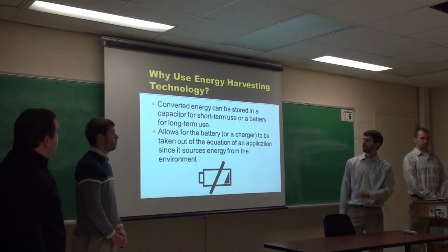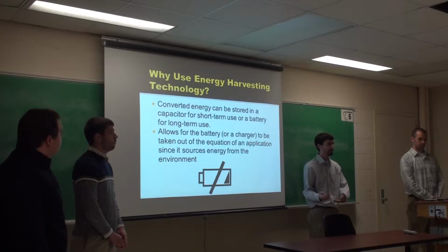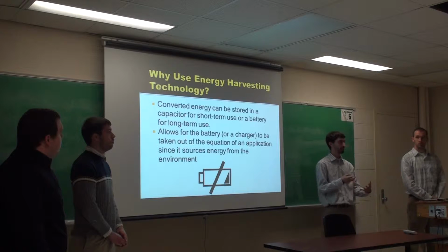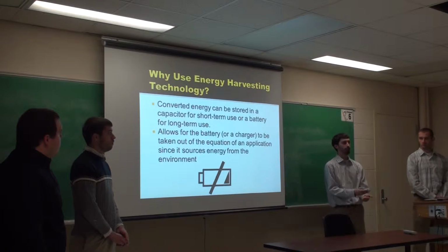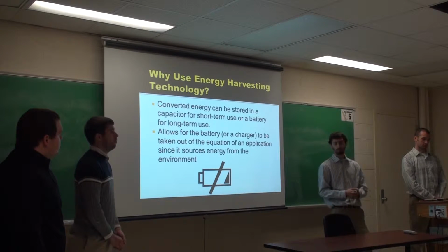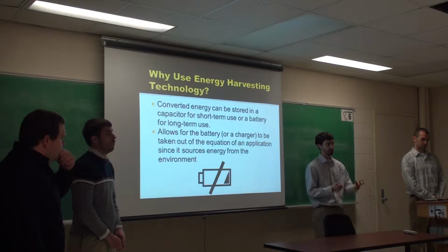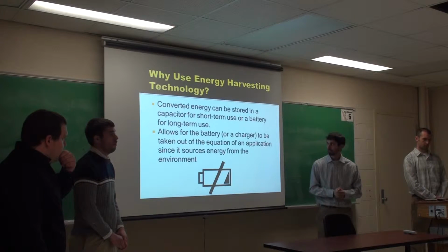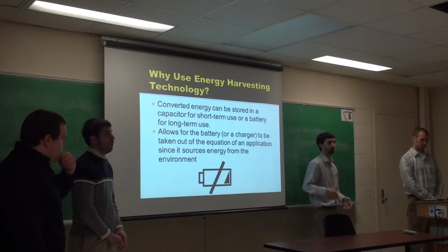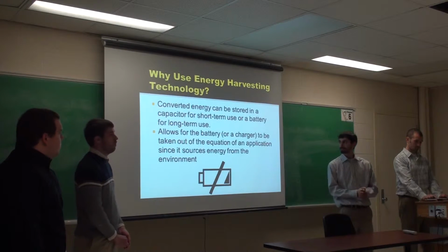We can further use this harvesting technology to store for later or use it now. In our project specifically, we are going to charge a capacitor and then use it to transmit a packet over the course of our network. We'll get into more detail of that later on, but we can also use it for storing in batteries and saving it for later. Again, this allows for a charger to be taken out of the equation because we can harvest it from the environment and save it for later.